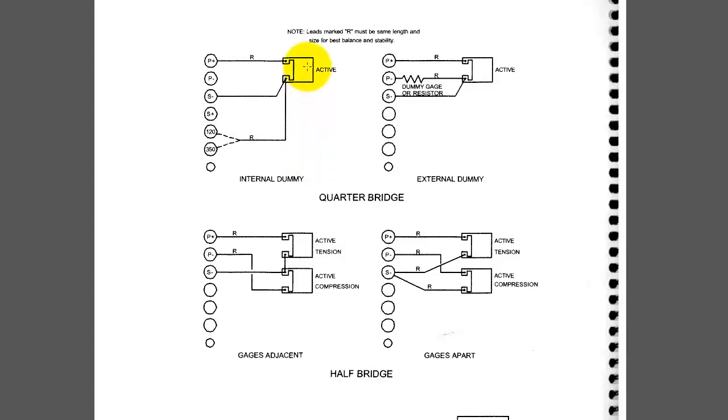So hopefully you can see conceptually how this matches the Wheatstone bridge configuration. Here's our active gauge with 1 wire with its resistance connecting to the power corner. We also have the second connecting wire with its resistance, lead wire resistance, connecting to the second or arm 4 on the Wheatstone bridge, and we can connect it here to make that a 120 ohm resistor, which is the same as the 120 ohm strain gauge you're using.